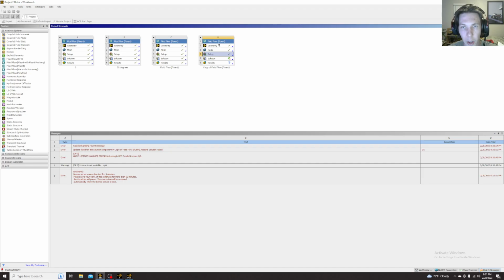Just update the angle, then update your mesh. You'll go to your setup, make sure that all the settings are the same, and then you run your calculation that way, and then it'll produce the results for that 40-degree angle that you changed it to.